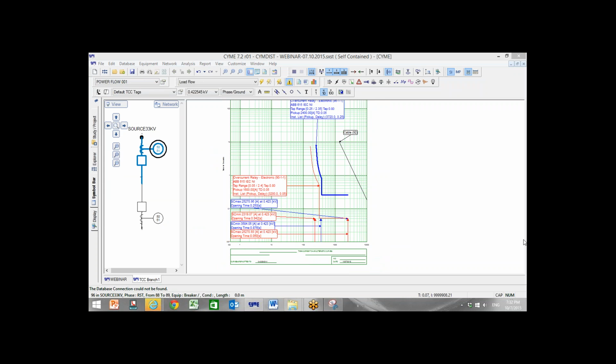Let's see what's the question. Mr. Nihar: in summary, downstream should trip earlier than upstream. Yes, it should trip earlier than upstream. Definitely, and the difference between downstream and upstream should be at least 0.2 seconds based on IEC, because you may have delay in operating, or malfunction, or activating upstream. So all of these upstream should trip at least 0.2 seconds after downstream time for tripping.